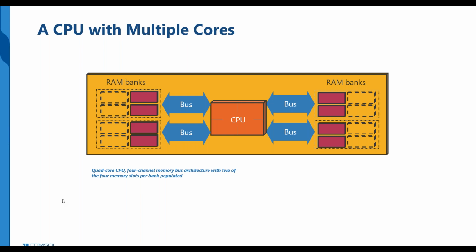So you have to use that in combination with a coarser mesh, and for wave problems it's important to still resolve the waves. So it's a tricky balance, but I can say this, that higher order for wave problems pays off. So linear order should not be used. Second or third order should be used. Maybe even higher.